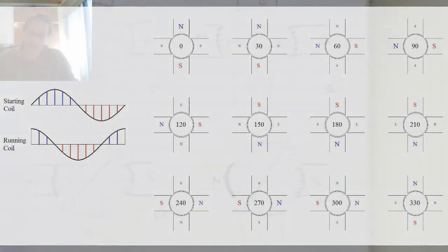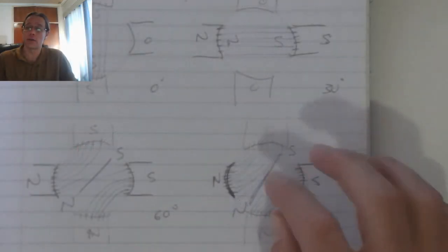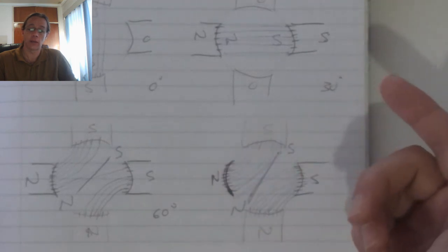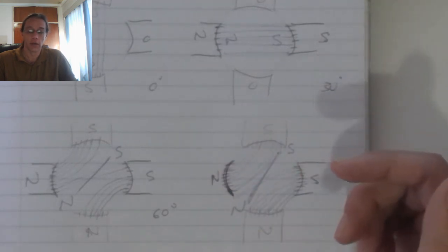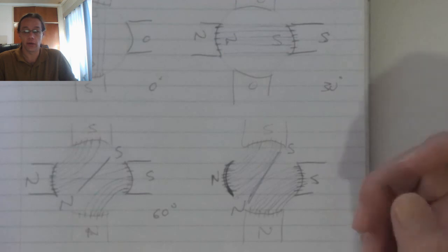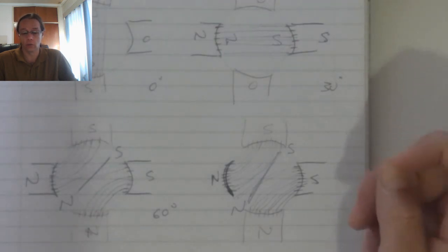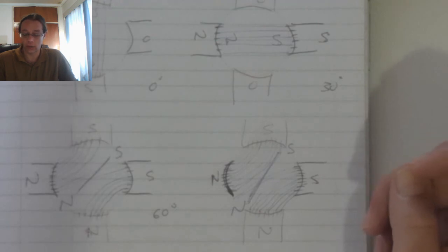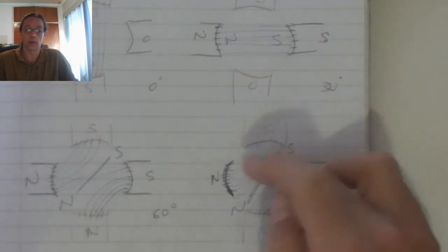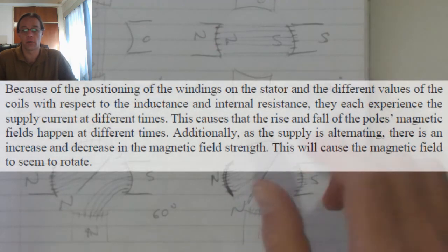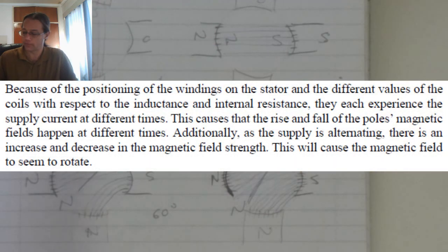Now the operation of the induction motor: these flux lines as they rotate will magnetize and allow conduction in the rods in the rotor. Those rods will generate their own magnetic fields, and those magnetic fields in turn will react with these magnetic fields, which has an overall effect of generating a rotating force on the rotor.